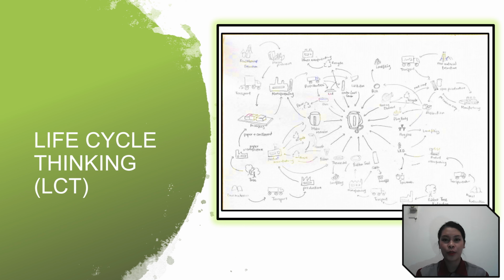The life cycle thinking process in this video consists of 15 components which are made from ferrous metal, non-ferrous metal, polymer, and natural rubber. The process begins with raw material extraction, then is distributed to production and undergoes processes such as extrusion, injection molding, and metal bending. The product is then distributed to the retailer. At the end stage, most of the polymer and metallic materials are recyclable, and certain plastic components are assumed to go to landfill.